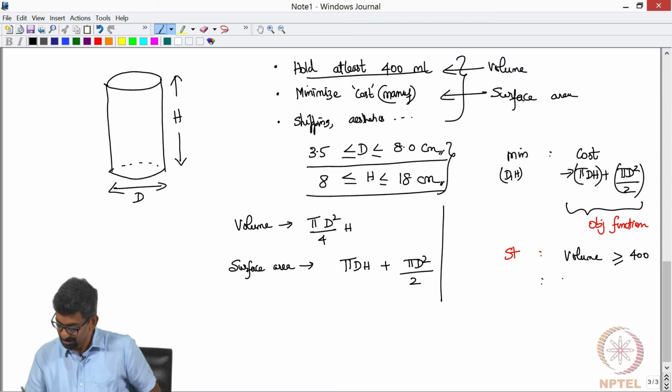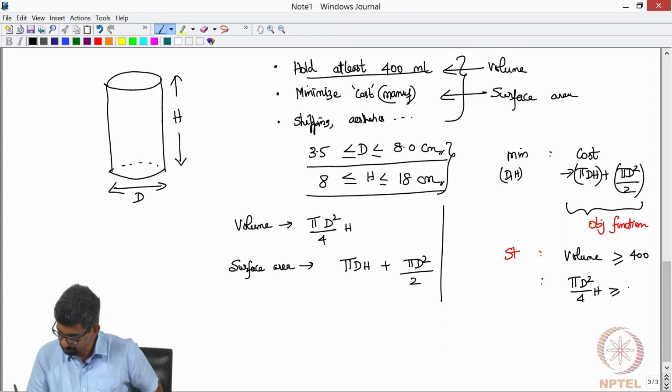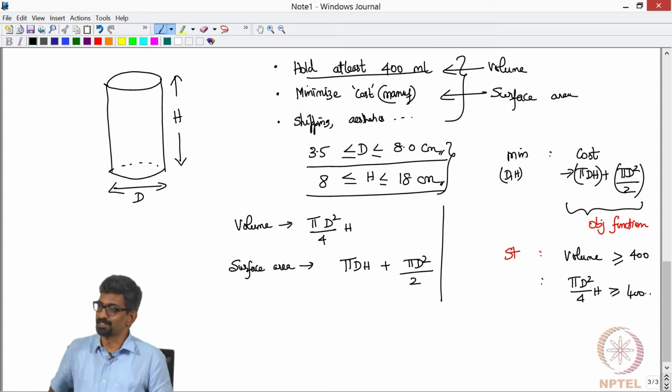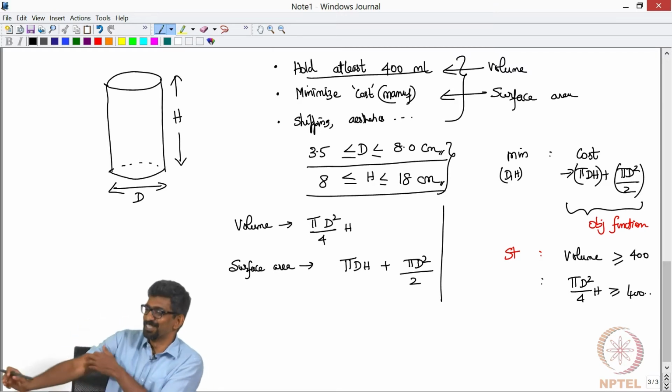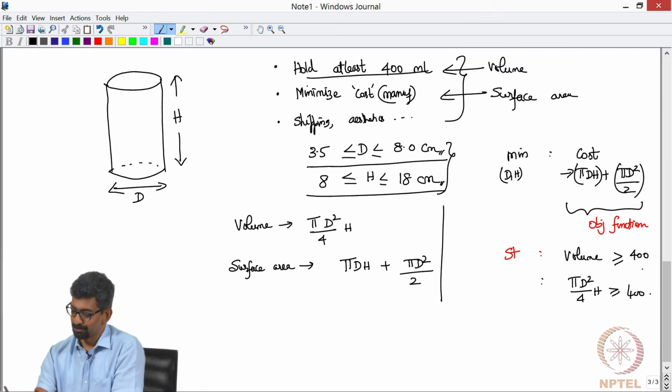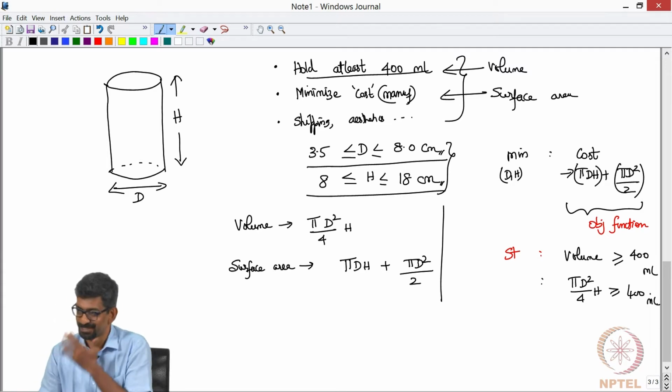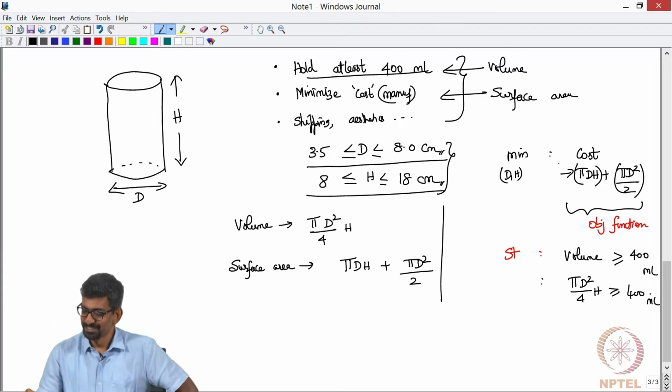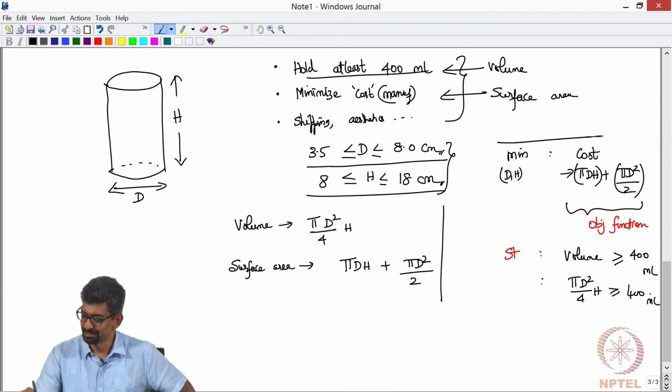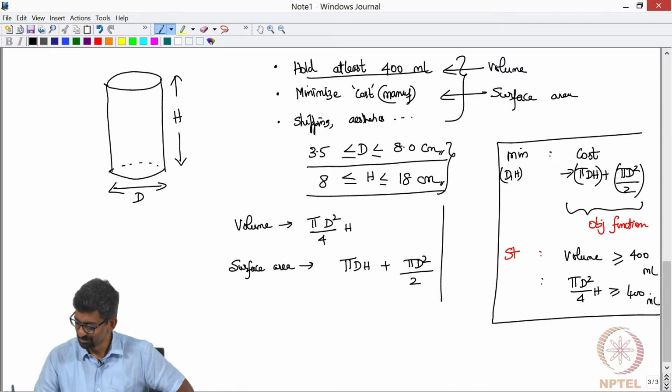Fine. So, you just need to plug in your equation here for this particular case. Do not get into complex conversions. It is either centimeter or meter. To make it generic I will put the units here. So, you want to minimize the cost such that this is done. This is the basic problem formulation, but now how are you going to solve this? It is all good, you have written it in a standard optimization format. Sorry, design variables are here D and H.